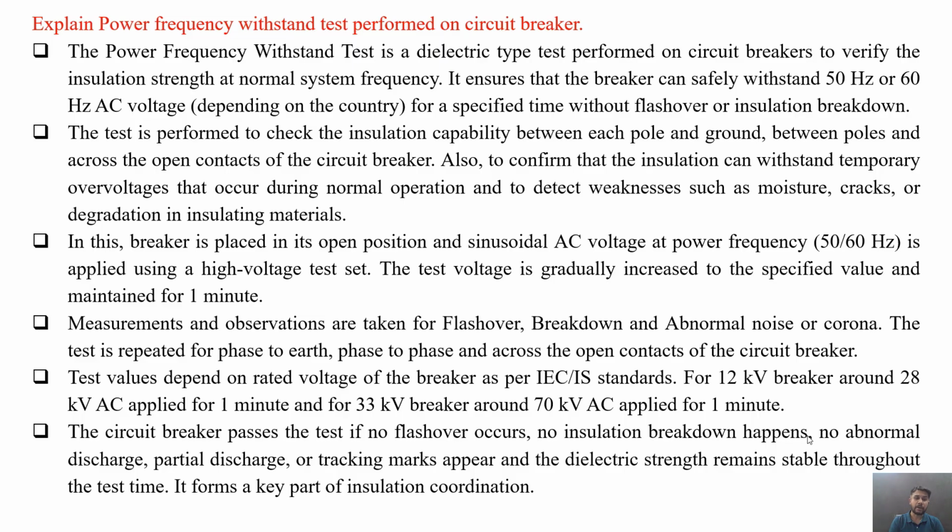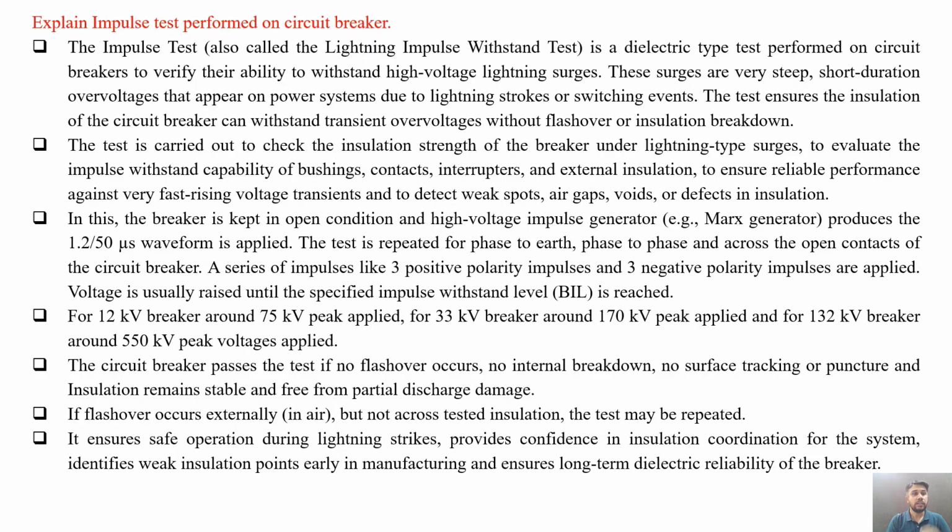The circuit breaker passes the test if no flashover occurs, no insulation breakdown happens, no abnormal discharge, partial discharge or tracking marks appear, and dielectric strength remains stable throughout the test time. It forms a key part of insulation coordination. So this is about the power frequency voltage withstand test performed on circuit breaker.